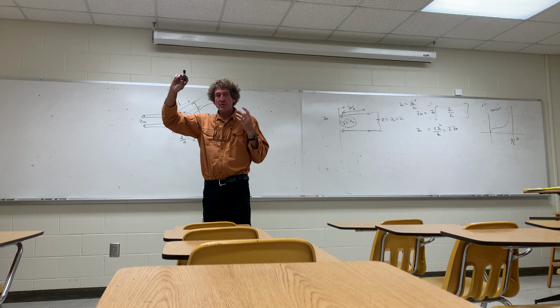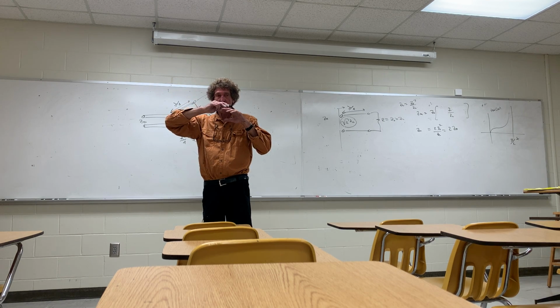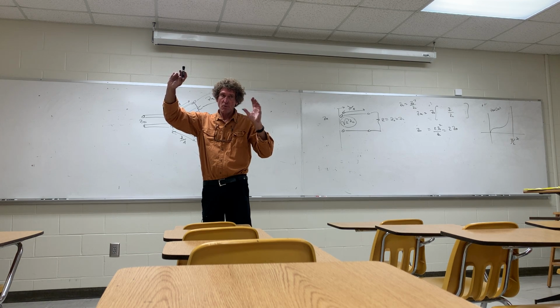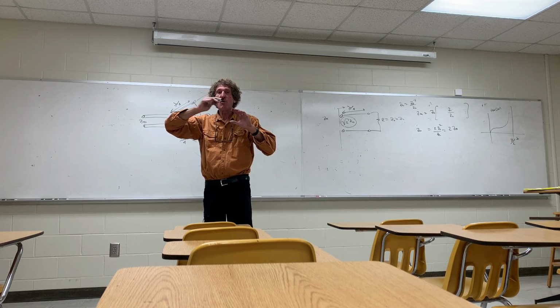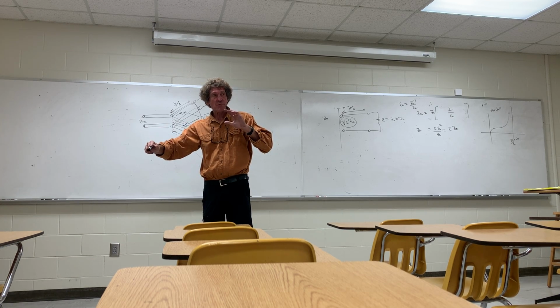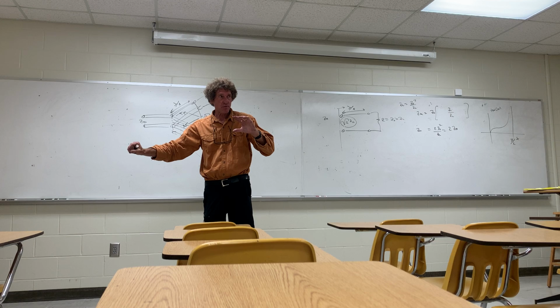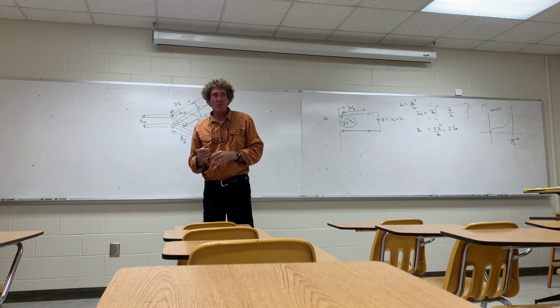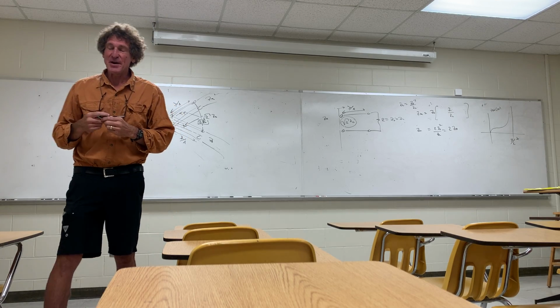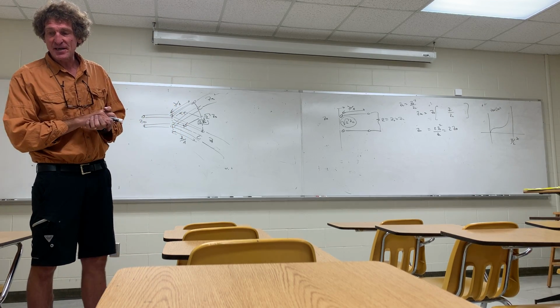When you have a coupler, a 4-port coupler, most of the energy leaves one port, like from port 1 to port 2. Some of it, a much reduced value, will bleed over to port 3, basically for synchronization purposes. They have a 4th port that really doesn't do much, but it is a second way to monitor it, and he shows you these things in his book.